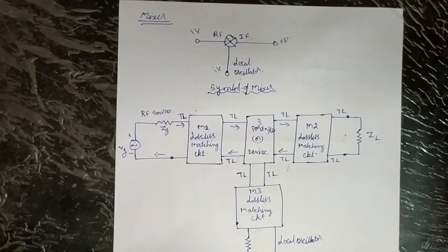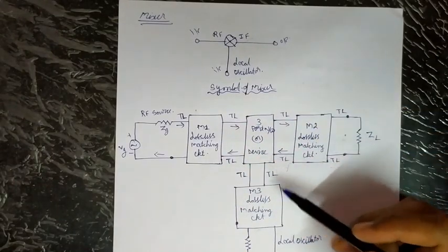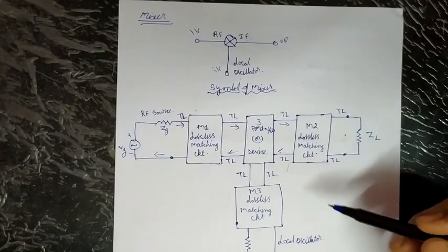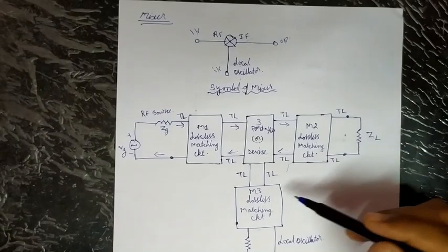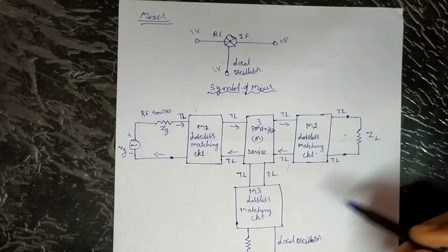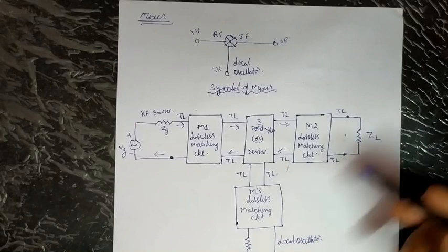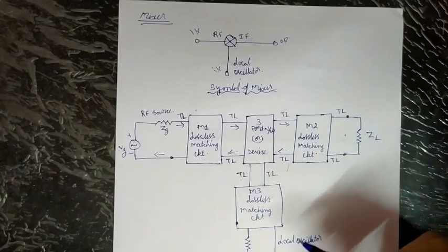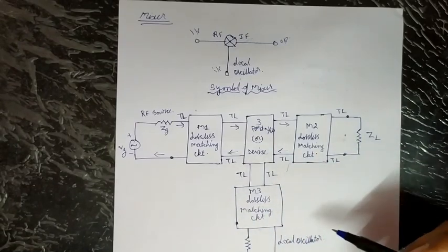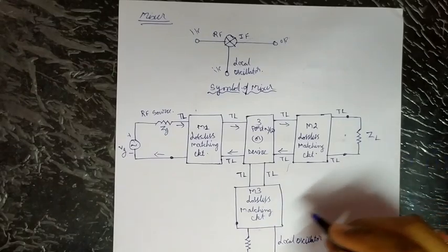So in general, the mixer utilizes one or more nonlinear devices properly pumped with an effectively large signal, like the local oscillator, to mix with RF signals in order to generate a spectrum of frequencies based on sums and differences of harmonics.